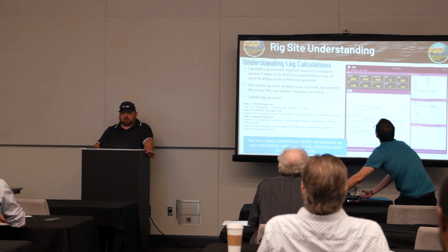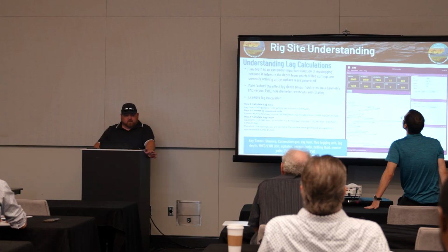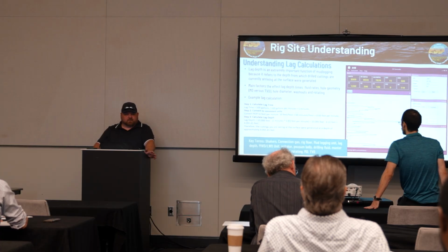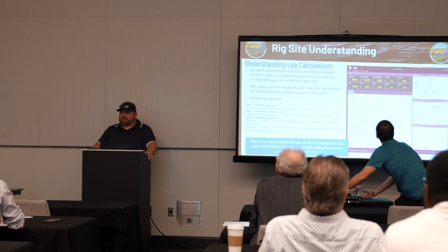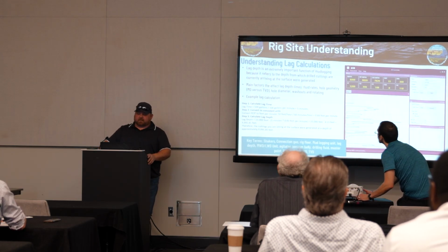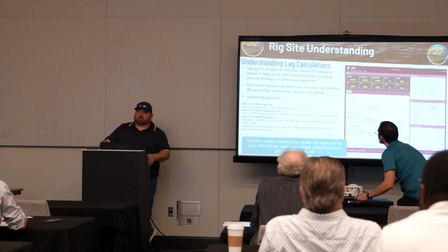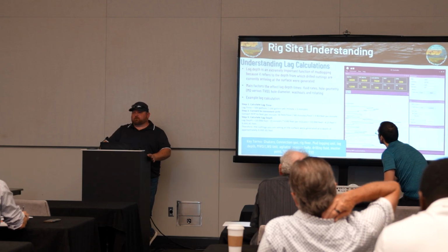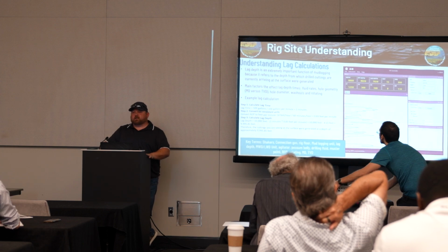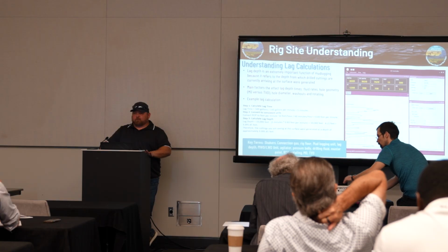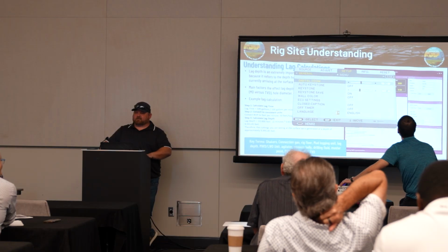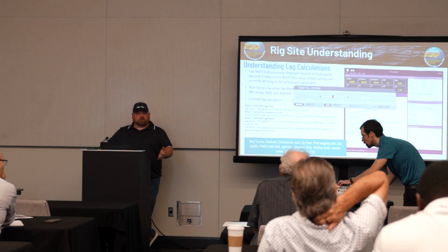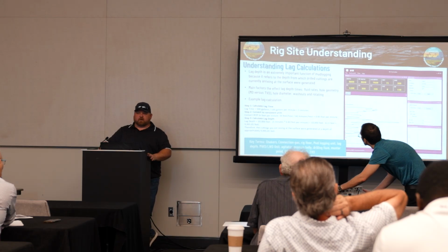But rough calculation. It doesn't account for washouts or turbulent flow, which is a little bit more advanced calculations. Somebody a long time ago came up with a bunch of formulas that probably said you'll never need math, and then here you go, now you need math. But that's a common mistake among people that aren't familiar with mudlogging, is the lag calculation. It's a real-time representation of the sample coming up the hole, but not where the drill bit is actually at. And the faster you drill, the further out the lag is going to be.